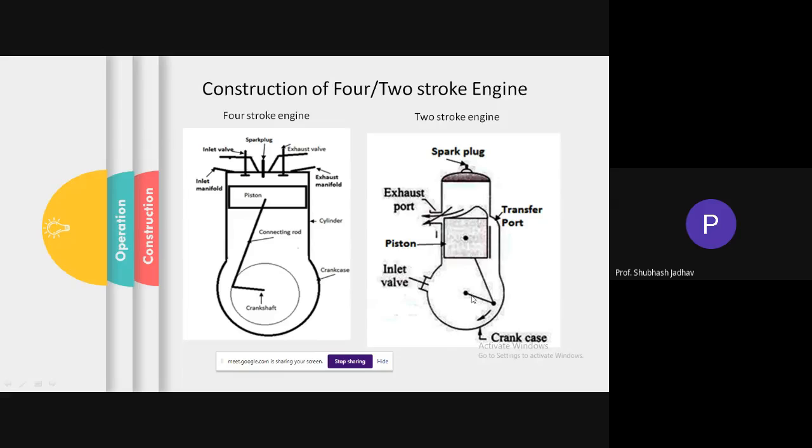Now, whenever the pressure on this side becomes lesser, this reed wall, or this particular plate, is going to be pulled towards this side to some extent, and there will be a gap between the hole and the plate, and we say it is open. Therefore, the gases can flow in. So this wall will be opening depending on the pressure over here. Whenever the pressure is negative over here, the wall is going to open.